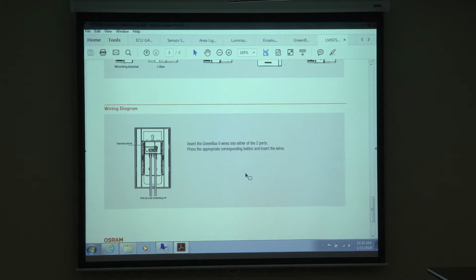So we don't know. When you see devices offline, you see a patch of them that are okay, that have no X's, and you see some of them with X's. So it gives you a range as to where the issue is. Now it's up to you to go into the field and see. You walk and you see a switch, for example, right? There'll be a light on the switch. You see a light? Good, it has power, right? No light, that means there's a break somewhere that's stopping it.